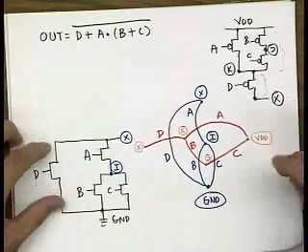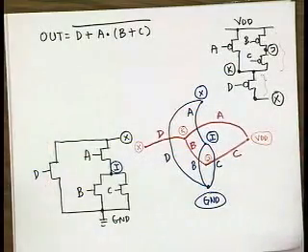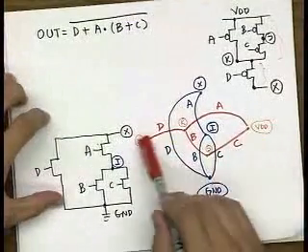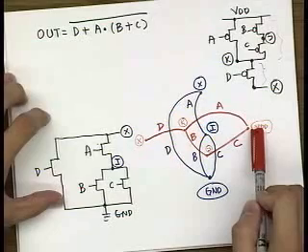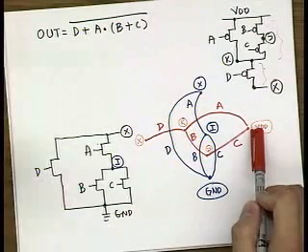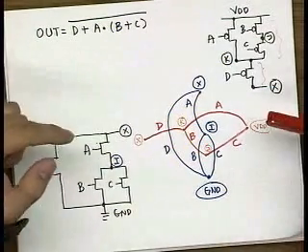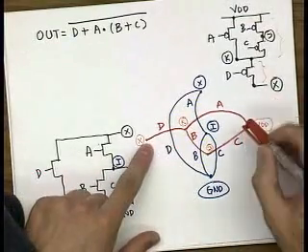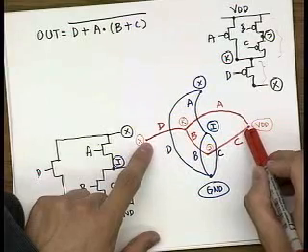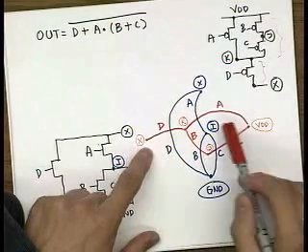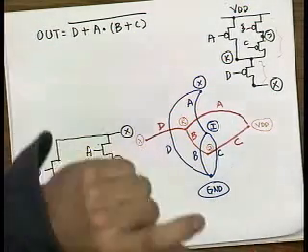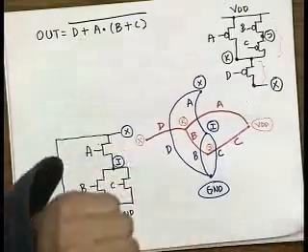Second, you have to construct the equivalent pull-up network. You do that by having a horizontal instead of vertical arrangement for the graph. For the pull-up network, you know that it has to connect VDD and X, so you put two endpoints, VDD and X. You can put them in any arbitrary order, as we just discussed. It will just change the order of your serially connected transistors.